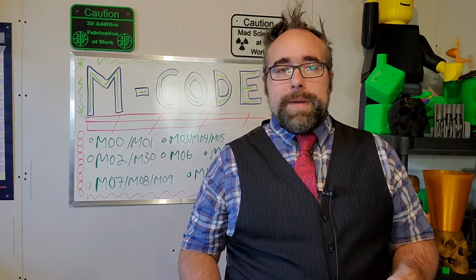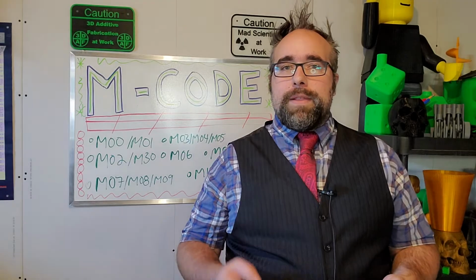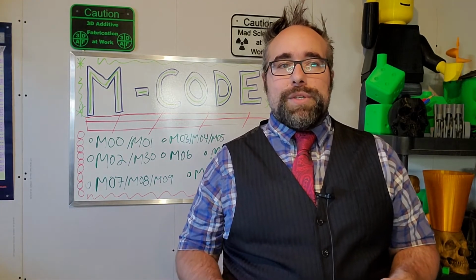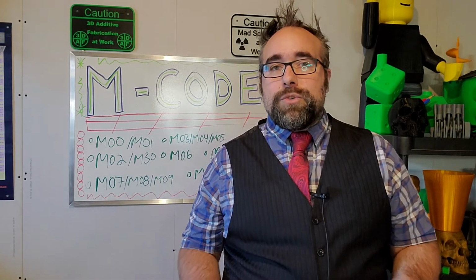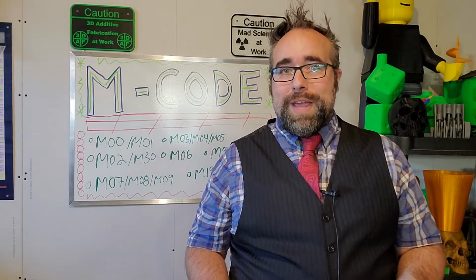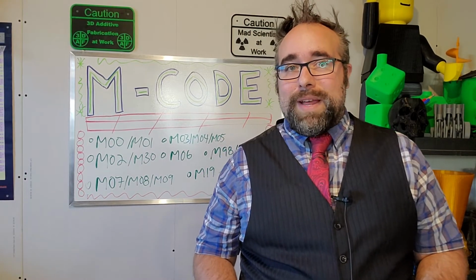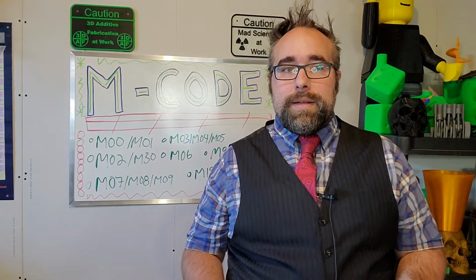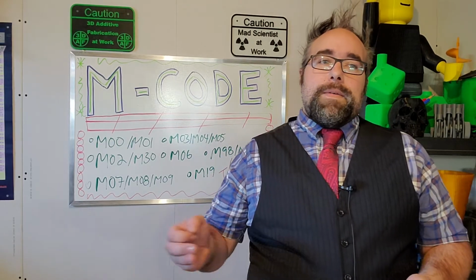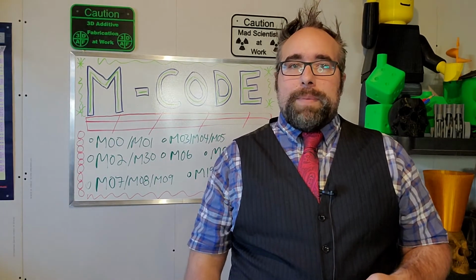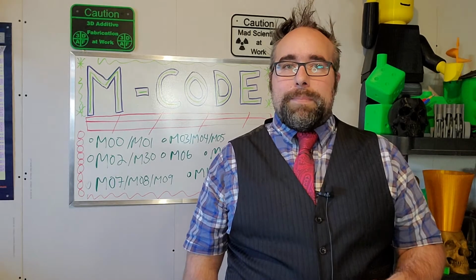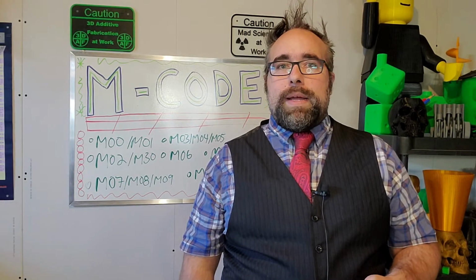Now, there are definitely times to use M04, especially with stuff like backing out taps and so forth, but in conventional machining, you require special tools to move counterclockwise and actually cut effectively, as most cutters are designed to cut clockwise. Finally, we have M05, which is spindle stop, which is literally hit the brakes, let's stop that spindle right now.